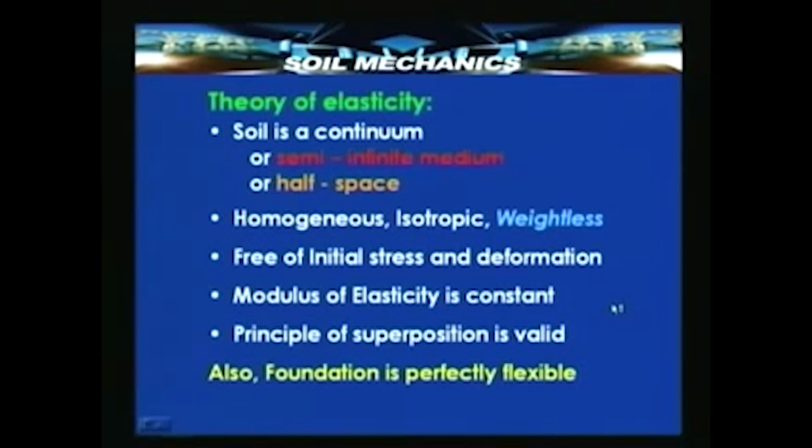get the total stress. But finally, a very important assumption that we shall be making is that this foundation is flexible, perfectly flexible. The importance of this has already been stated, that is, when we have a flexible foundation, we have uniform contact pressure, and all the derivation, all the theory, all the methods that we shall be seeing now are all valid for uniform contact pressure at the foundation soil contact.